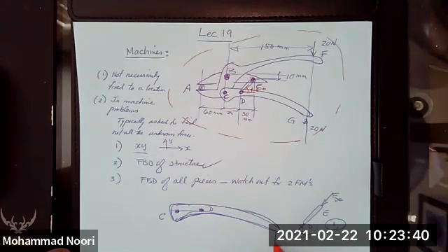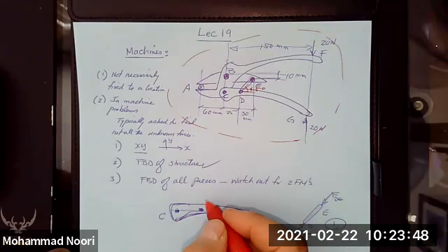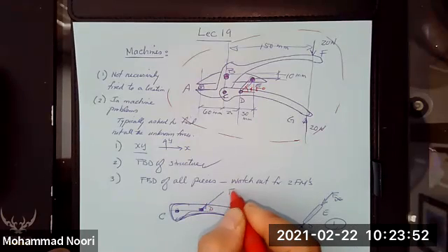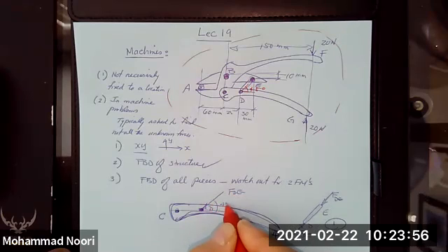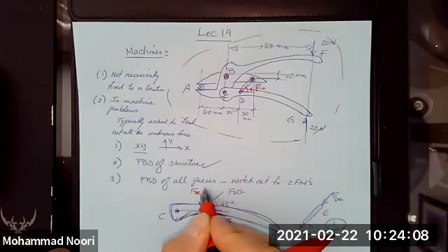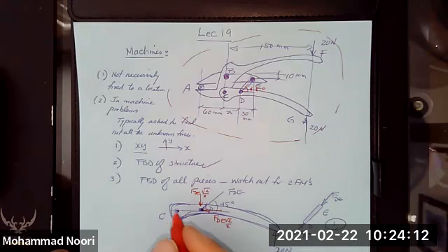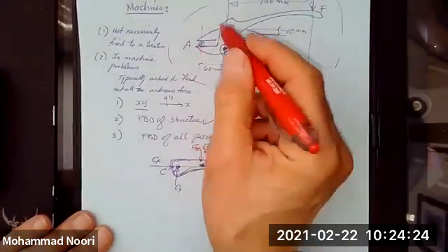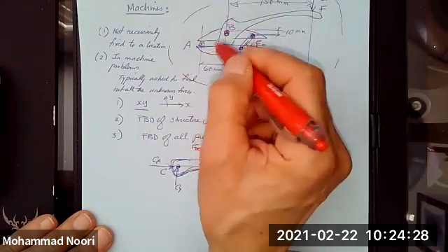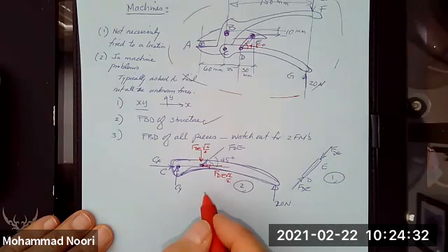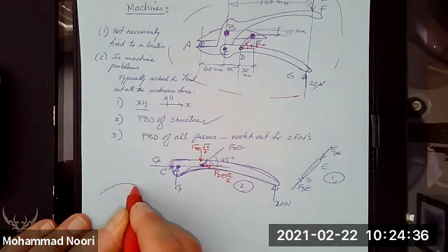So at point G, you have an external load of 20 Newton. Point D is from here, so this is that force FDE acting at 45 degrees. Let me resolve that into its components. So this is FDE square root 2 over 2, cosine of 45 degrees. And at C, you have these two unknowns, Cx, Cy. So this is free body diagram 2. So what else do you have? This guy, the free body diagram of the blade and this piece. Let me do the blade first. So you have this blade here.